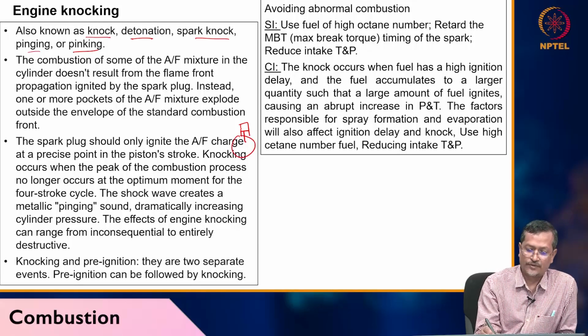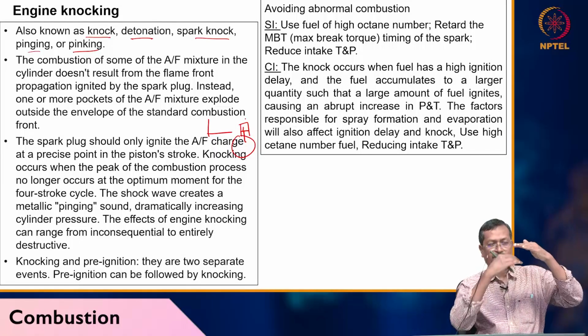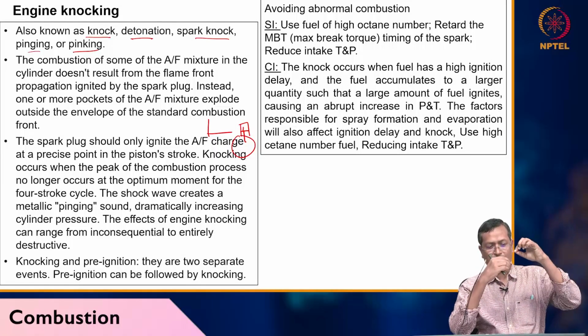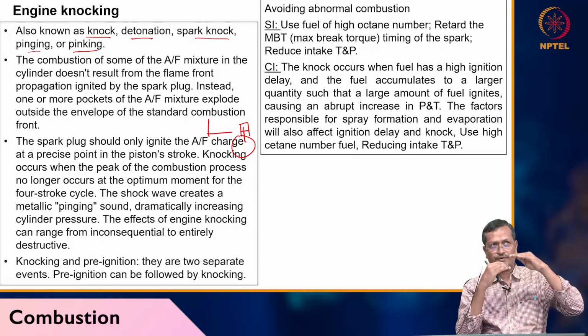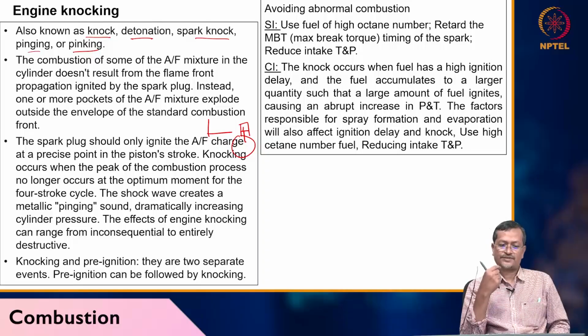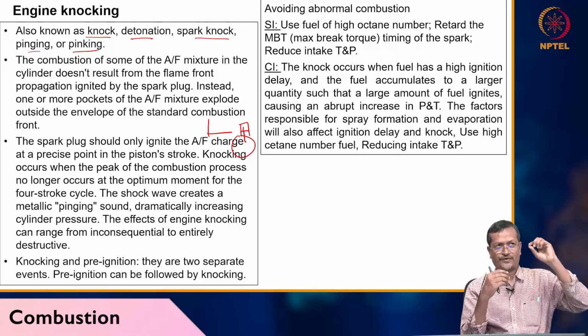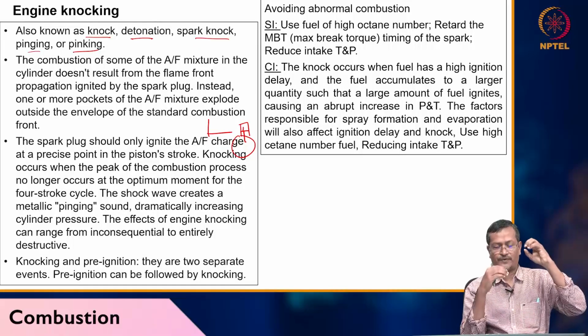You have the piston cylinder arrangement. Now you are compressing the cylinder gas. In an SI engine especially, you are compressing the air fuel mixture, then the spark will happen. But before the spark starts, your combustion started because of a certain issue. Let's say the engine is very hot, then before the spark plug fires, your fuel will be burning.